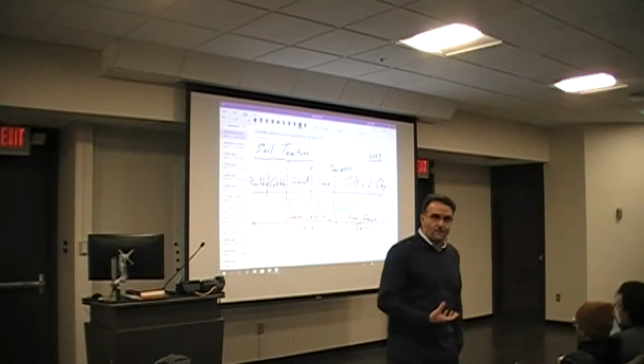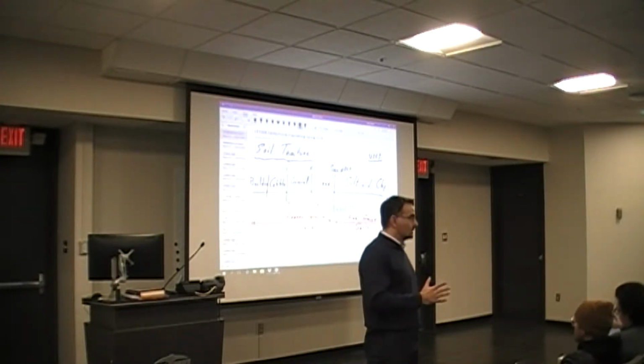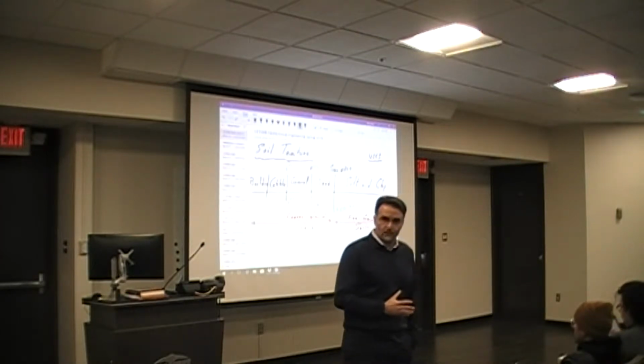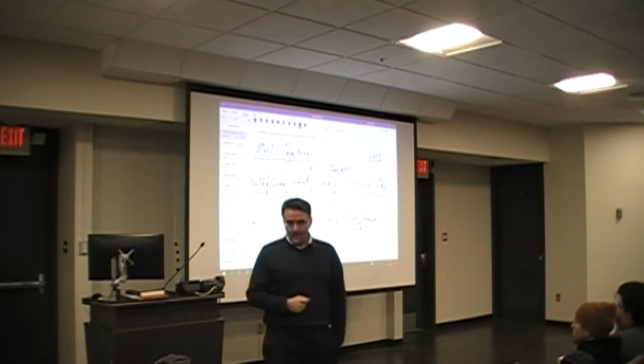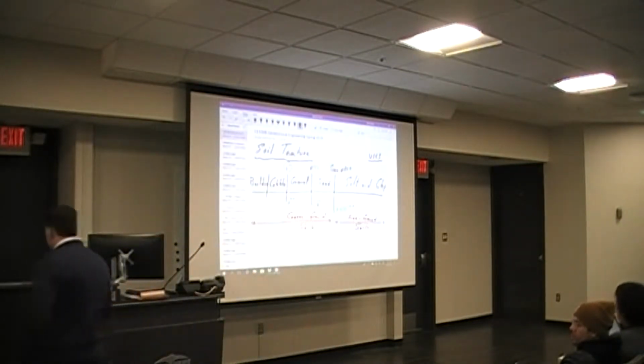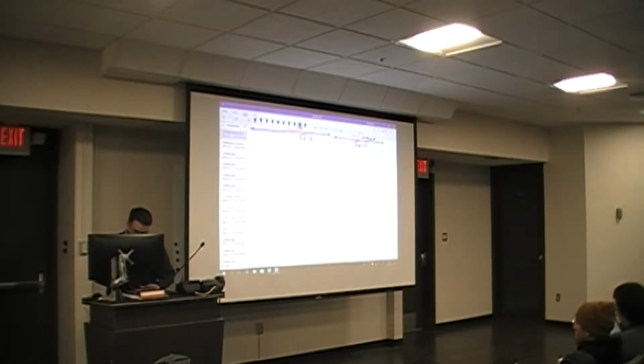If you have a mixture that has less than 50% passing sieve 200 material, that is called coarse-grained material. The engineering behavior of coarse-grained material and fine-grained material are essentially very different from one another. We're going to separate them and talk about them individually. But for that, we need to figure out the exact definitions of each of these individual components. So let me quickly write down what we talked about in terms of the definitions before we move forward with characterization of the coarse-grained material.